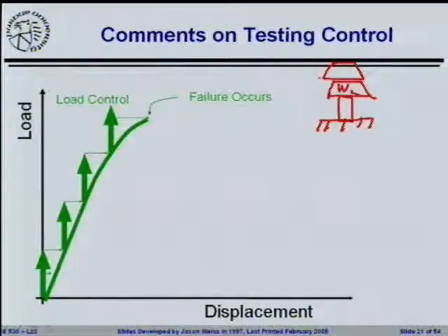You're saying, I'm going to increase the load on the specimen in a controlled fashion. If you were to put on 10 pounds every minute, it would be exactly what we tell most of our new servo-hydraulic mechanical testing machines to do. Let's increase the load, and then we measure the displacement. Increase the load, measure the displacement, increase the load, measure the displacement, increase the load. The material can't handle that increased load anymore, and we are at the condition Mohammed so eloquently described as kablooey.